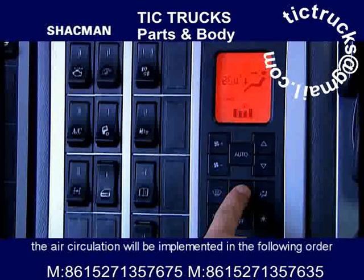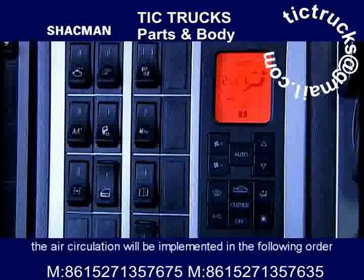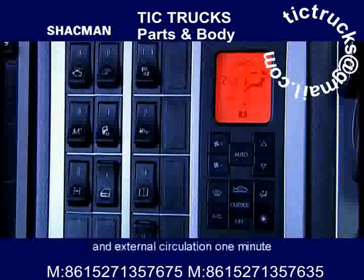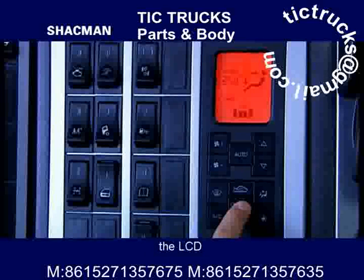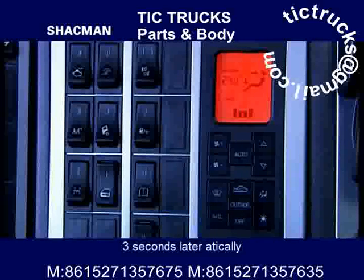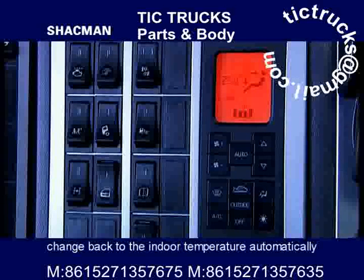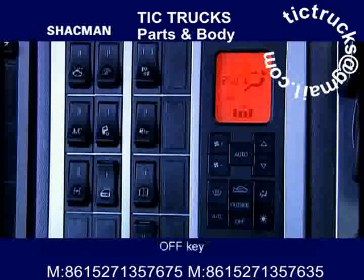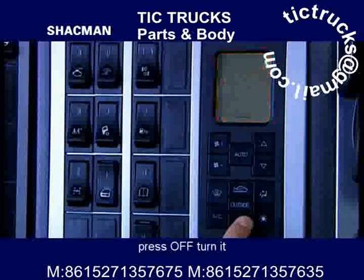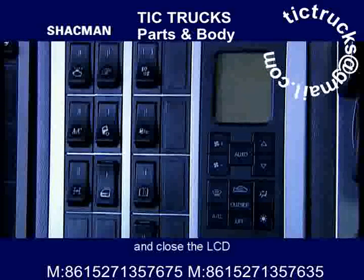Air circulation will be implemented in the following order: internal circulation for 15 minutes and external circulation for 1 minute. Press the key. The LCD liquid crystal display will show the outside temperature. 3 seconds later, it changes back to the indoor temperature automatically.